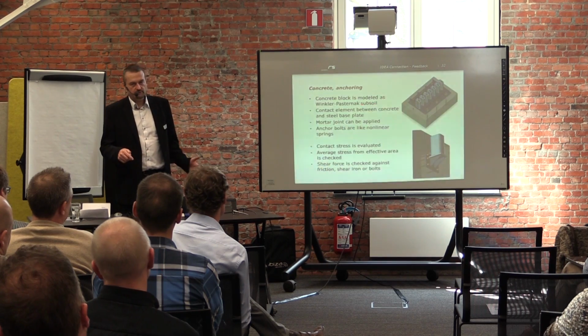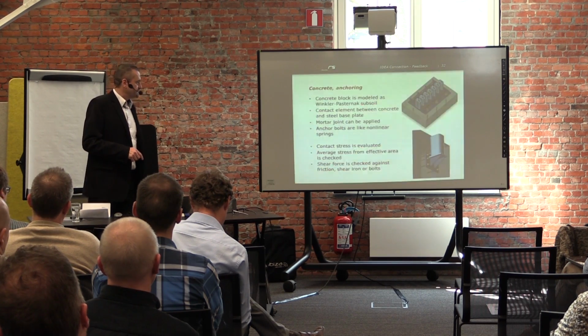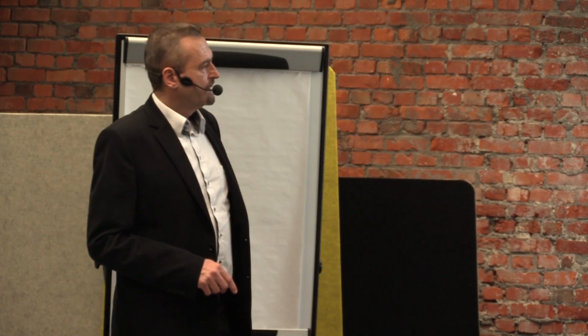It is the same as what you do when you design buildings, and in fact, in each point of the mesh on the base plate, we have some spring, which represents the stiffness of the concrete block. We have contact elements between the plate and this concrete block.